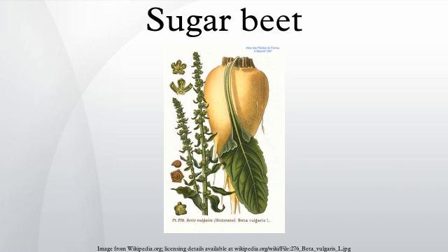If the beets are to be left for later delivery, they are formed into clamps. Straw bales are used to shield the beets from the weather. Provided the clamp is well built with the right amount of ventilation, the beets do not significantly deteriorate. Beets that freeze and then defrost produce complex carbohydrates that cause severe production problems in the factory. In the UK, loads may be hand-examined at the factory gate before being accepted.